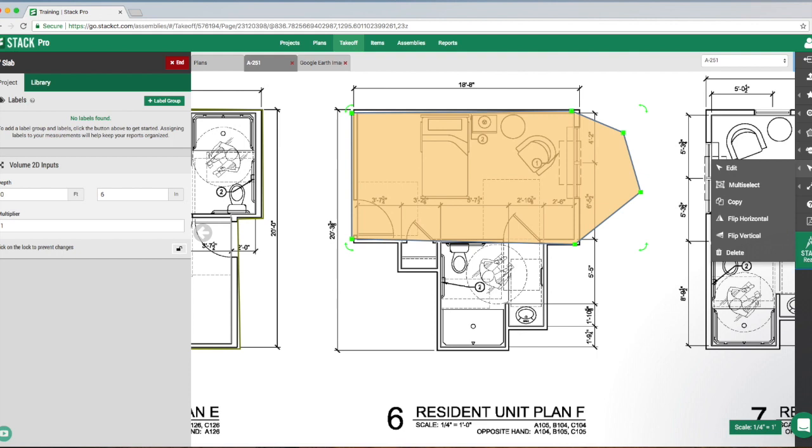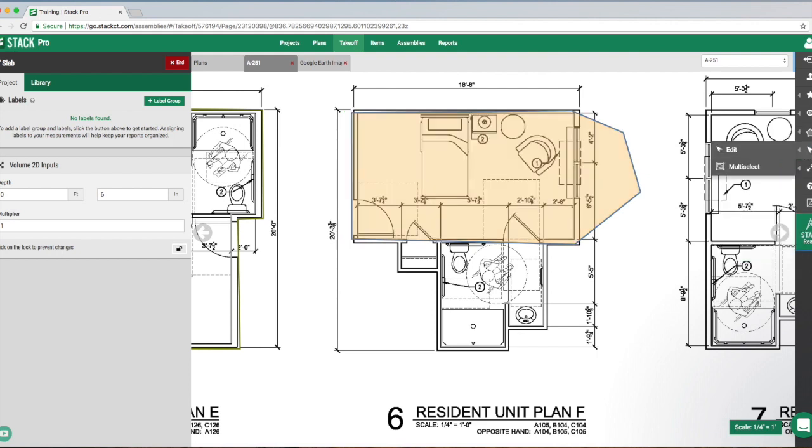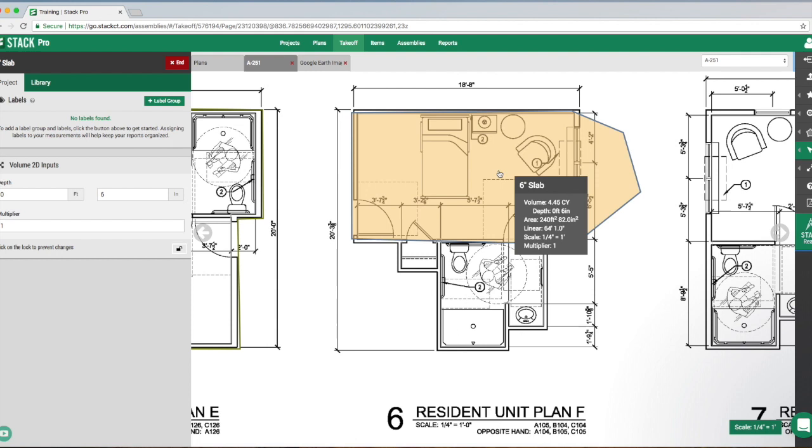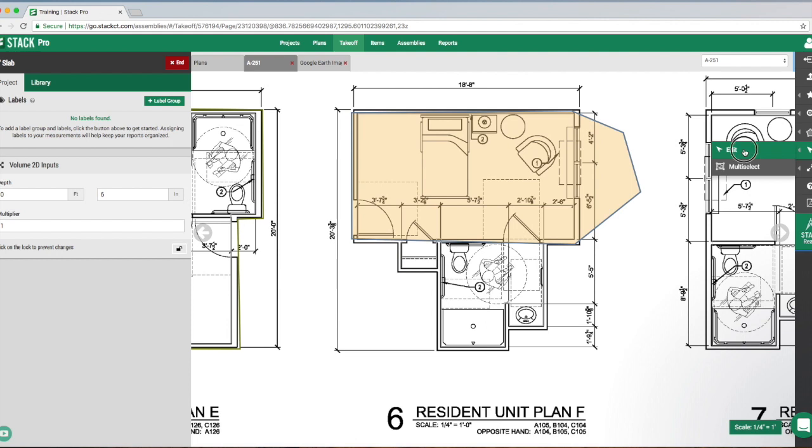We can also remove a negative space. So we have a hidden tool here to be able to remove negative spaces. It's our little power saw icon. It's a hidden tool most of the time, but say I was going to remove this bed area. So in the real world, this would be, you know, a parking lot, and we're wanting to remove either a center island, or we're working on top of a roof and we wanted to remove an area for a rooftop unit. I'm going to go over here again to edit mode.